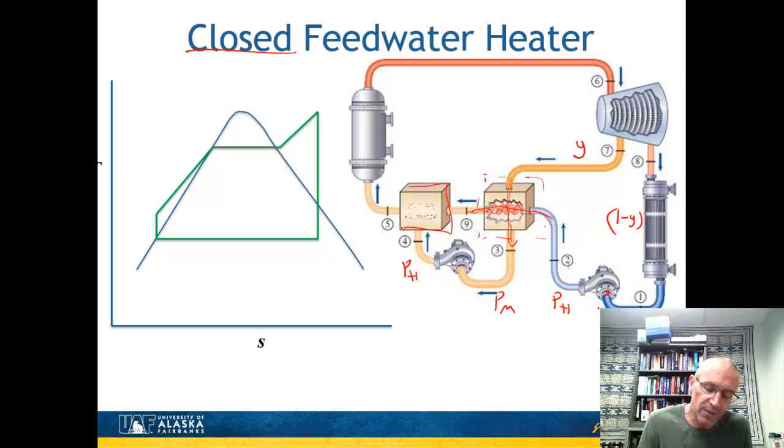And then over here, this is more or less like an open feed water heater or just a mixing tank. Again, it's just a big, large tank where the two get mixed together. And so after I've brought it up to the high pressure, I can then mix them together, and it goes into my boiler here.